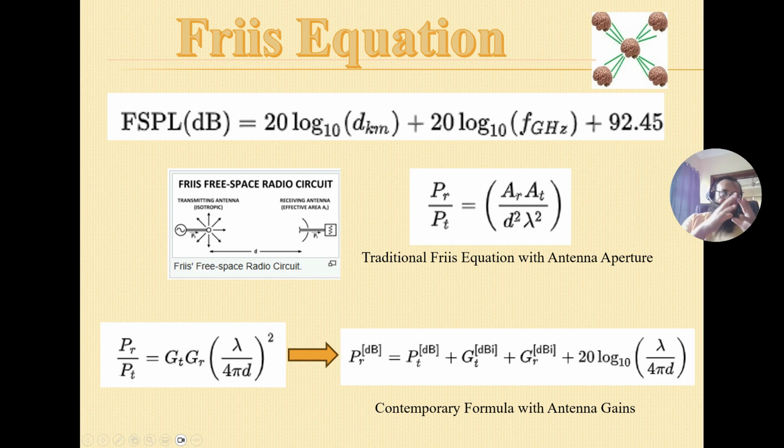So there's a difference. When you have an isotropic antenna, a very little power is going in the front direction because power is spreading in all directions. But when you put a dish on the back of the antenna, it is transmitting in all these directions, but whatever is transmitted is being directed to the front of the antenna. So you typically have a gain. I mean, now the power which is going in the front direction is much more than it was going when it was a simple isotropic antenna without any directivity given to it.